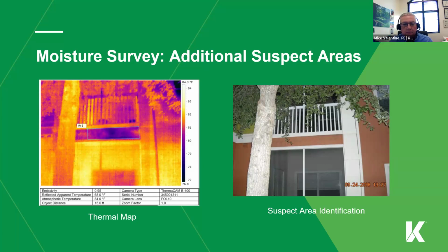I mean, some codes have changed depending on the age, but for the most part, if you have existing drawings and the existing information about that header beam that goes across there, 9 times out of 10, we'll probably put it back with the same. But if we don't have anything, then yeah, we have to do our own little homework and do a couple more calculations to figure out how we would design that today, and then provide that beam header size.